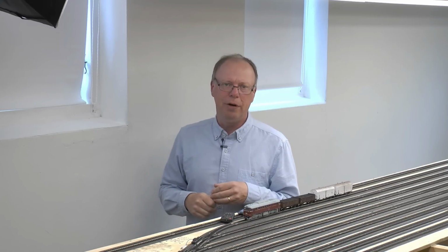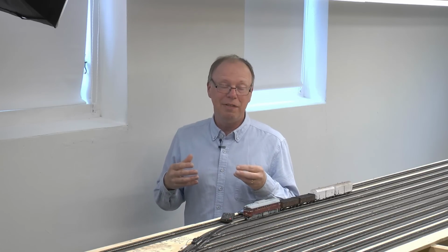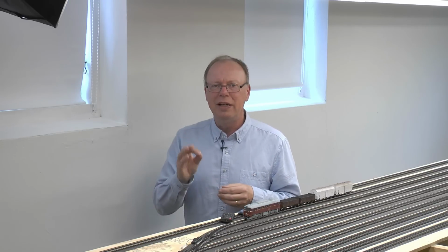And also I found that it takes a bit of, I would say, skills to get nice prints of tiny objects on a filament printer. You have to change nozzle, you have to fine adjust the temperatures, etc. So, you know, if you have those skills, no problem. Then this will print for you as well.